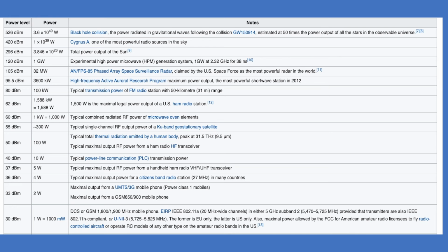For example, when I tested handheld radios, you'll notice that I had an RF tap on there. The spectrum analyzer I use can only take a maximum input of 20 dBm. Any more than that, and it will potentially smoke it. So that's why I've always got an attenuator on there, to clamp that signal way down below 20 dBm. You can see that even at 30 dBm, that's one watt, which is more than the spectrum analyzer can handle